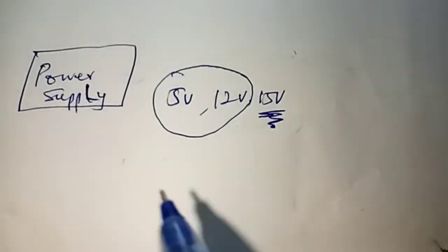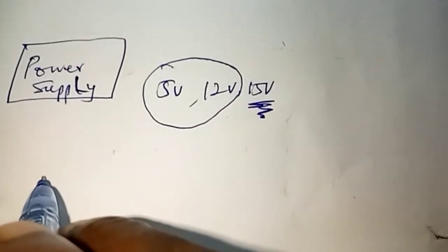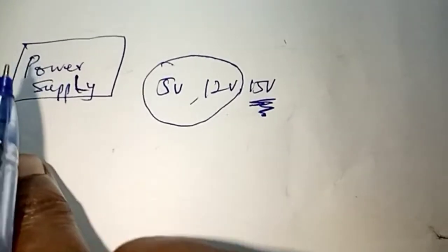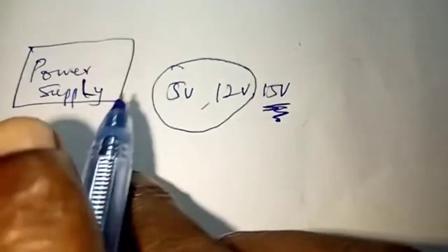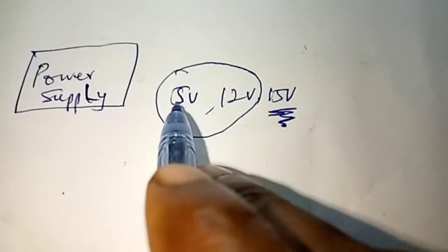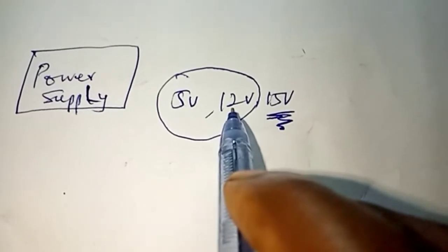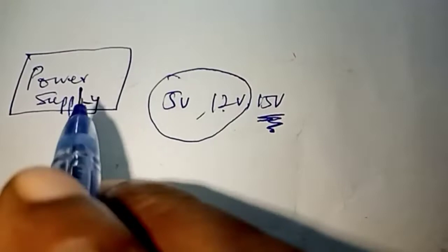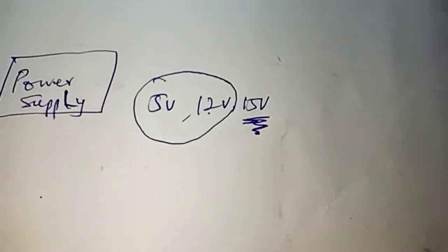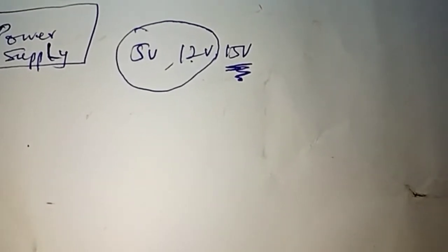So this power pack will involve a step down, because your normal light is 220 volts and you step that 220 down to 12 volts, because you need 5 and 12 volts, so you go for the maximum voltage, meaning you are using a 12 volt transformer to step it down. So after the power supply, think about how an AC circuit diagram works.